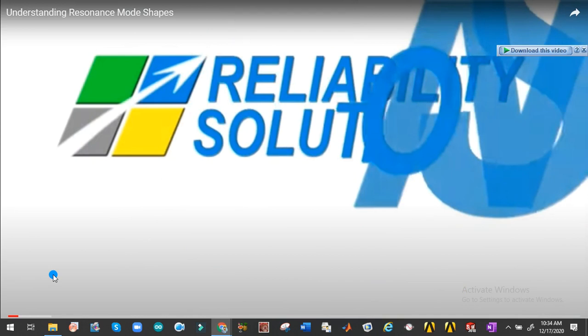Okay, now this is the scaled down model of a steam turbine flexible rotor. You people can see why we need to find the mode shapes or critical speed. You have always studied what the critical speed is and so on. So why do we need to find out the critical speed? Here you will see that there are multiple critical speeds that one particular flexible rotor is withstanding. So we need to find out those numbers of RPMs.